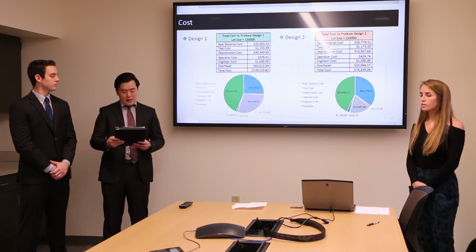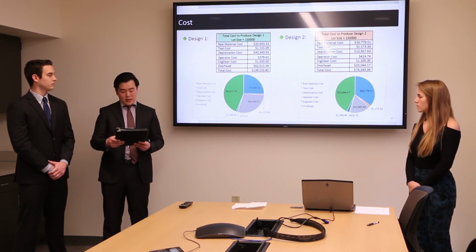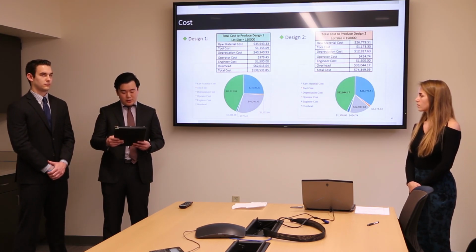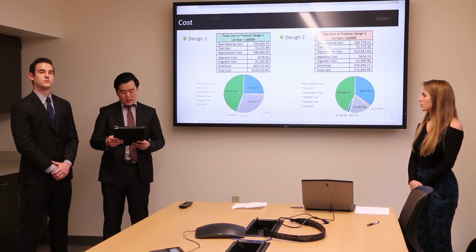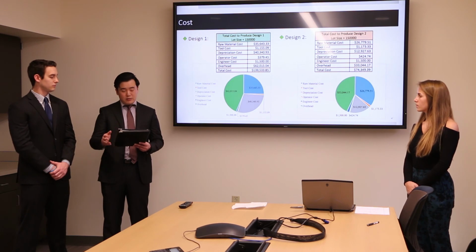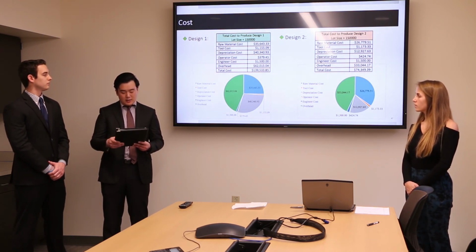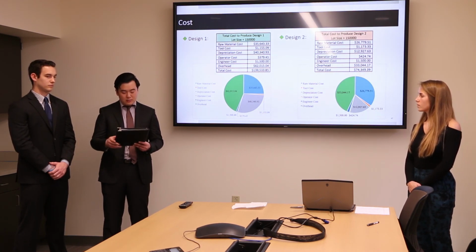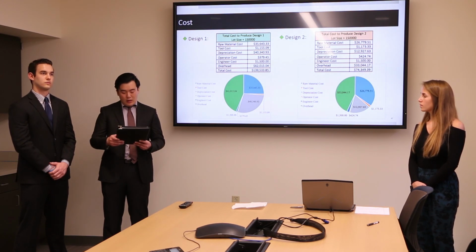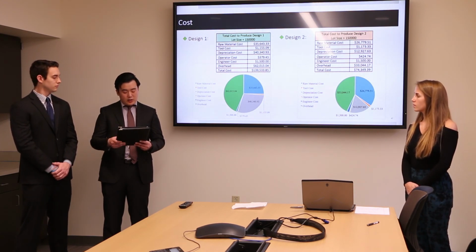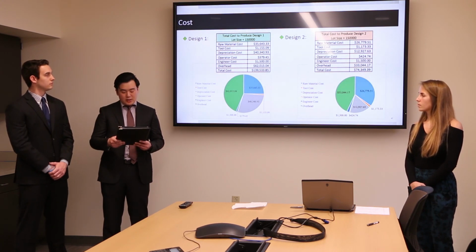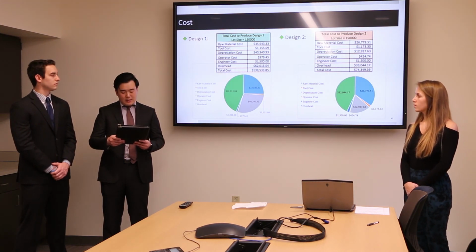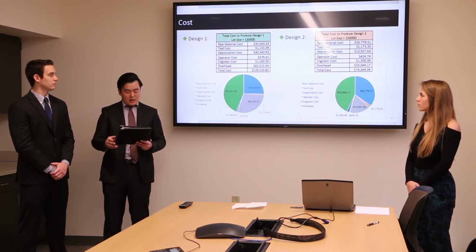Right after we finished design 1, we applied the complete total cost analysis algorithm onto the manufacturing parameters. We observed that the cooling time is the most influential factor regarding the total cost. Considering that the cooling time is directly determined by the maximum wall thickness of the injected parts, we decided to reduce the housing wall thickness and replace the Y-shaped stem with the T-shaped stem to shorten the cooling time. By doing so, both depreciation costs and raw material costs are greatly reduced, since the total volume of the injection and the cooling time are decreased significantly. Even though the mold manufacturing time increased, the total cost is reduced by a great amount.